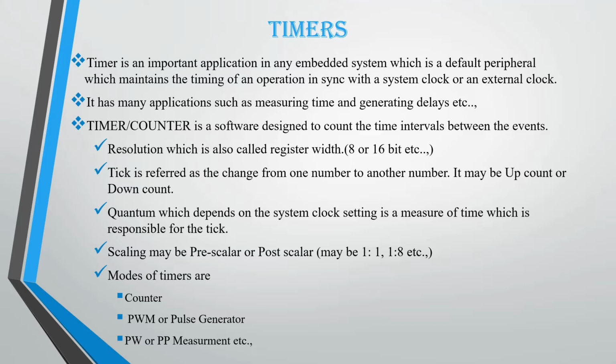Quantum, which depends on the system clock setting, is a measure of time responsible for a tick. Scaling is a factor we add based on user requirement, whether it is pre-scaler or post-scaler. Modes of timer are counter, PWM, that means pulse width modulation generator, or pulse measurement.